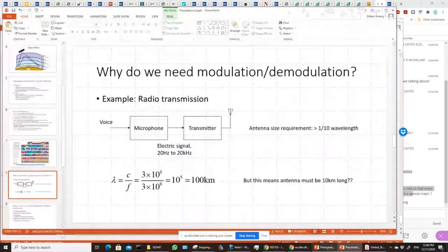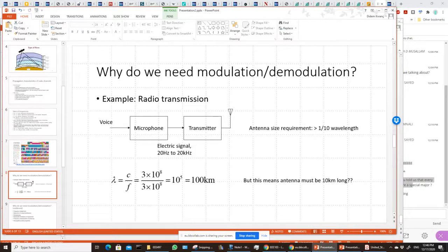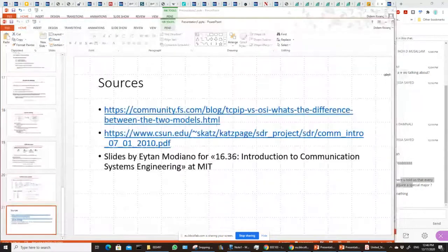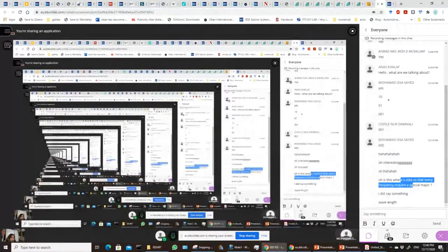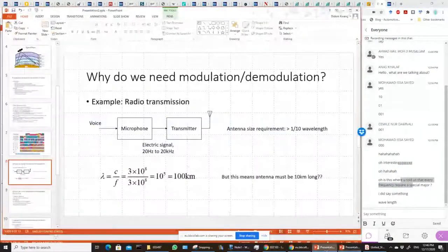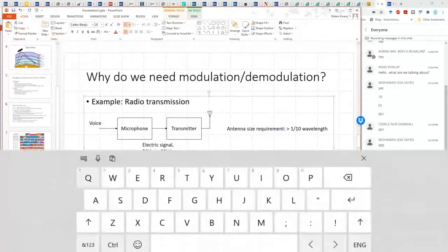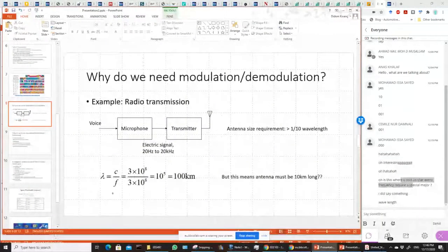Well, there's a simple formula for it. You can calculate it. Lambda is c divided by f, where c is the speed of the electromagnetic wave across the wire or the air or wherever, generally the speed of light. Might be slightly slower, depending on the thing. You will learn about that in electromagnetics class. Yes, exactly, lambda is the wavelength. The spatial wavelength. Because when you say wavelength, sometimes we think, oh, well, it's varying in time too. No, this is the spatial wavelength, right?